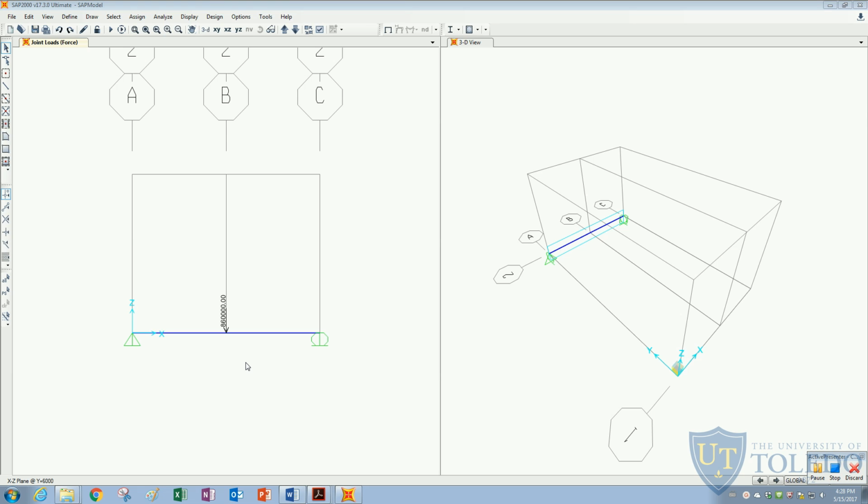In a force-based analysis, we can't, because like I said, we keep increasing the force and calculating the displacement of the element. Since it can no longer take any more force, once we reach the peak of our element, our force-based analysis can't calculate the post-peak response of the element. So you might think, then let's always use the displacement-based because we want to see the full response of the element.